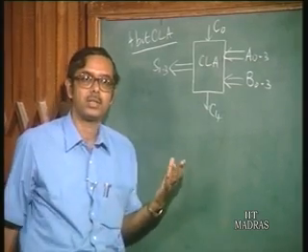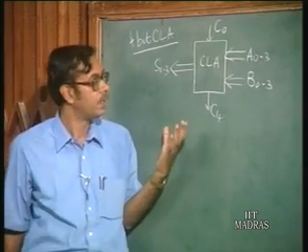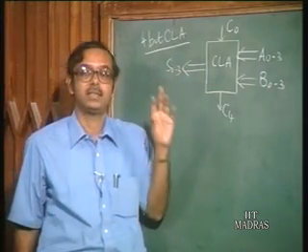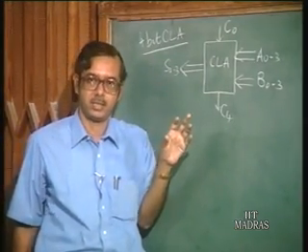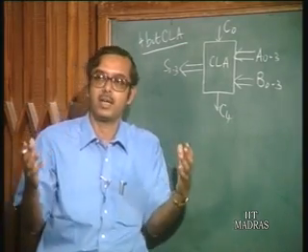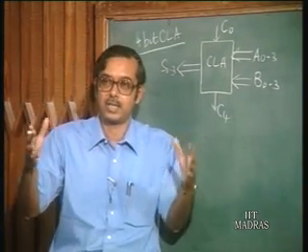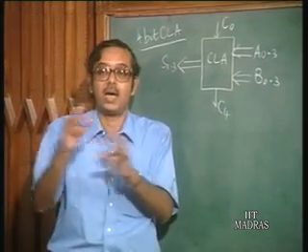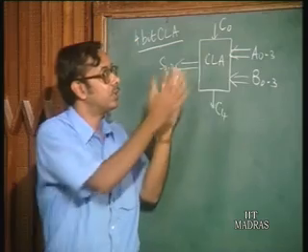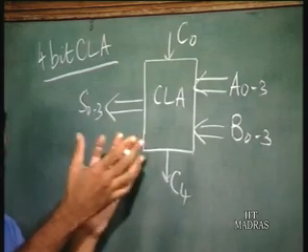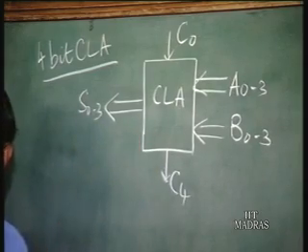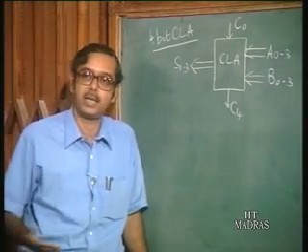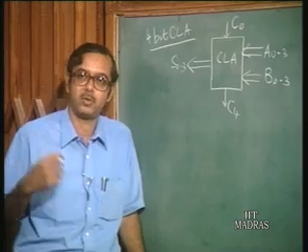That is very important even in the case of VLSI, because the philosophy in VLSI design is that you require repeatable structures, because it is very difficult to actually design every transistor in a VLSI. So, you must have structures which are repeatable. And this is a totally repeatable structure which you can go on adding to obtain, for example, a 32-bit adder or even a 64-bit adder or any multiple of 4-bit adders.